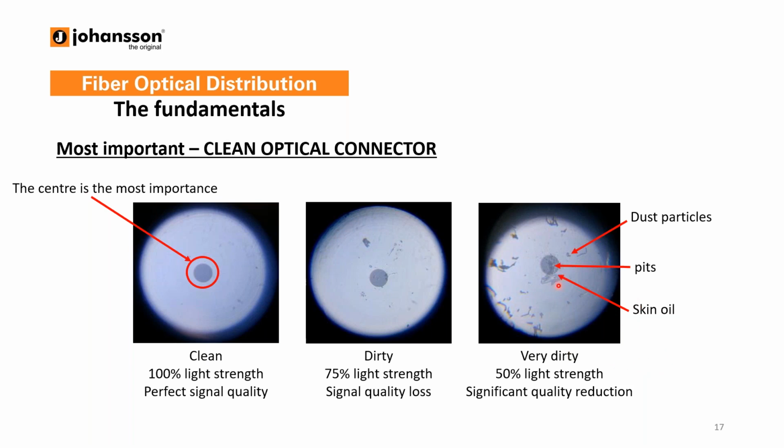So basically in this case it's the same as putting an attenuator in your network. It's the same if you touch the cable with your fingers. So this is something that I want to stress, that you always keep your cables clean. It will make your life much easier, and you will be able to reach the number of splits you have in mind. If your cable is dirty, you can always use special tools to clean it. There are many tools for that. So it's recommended to keep your cables clean.